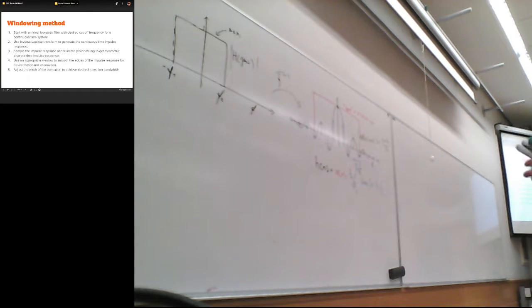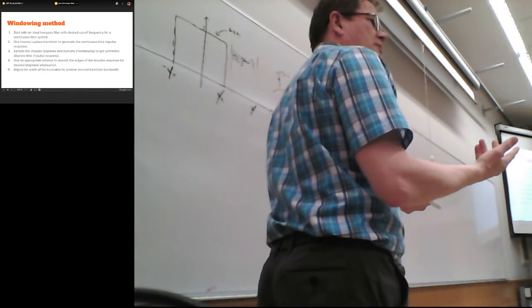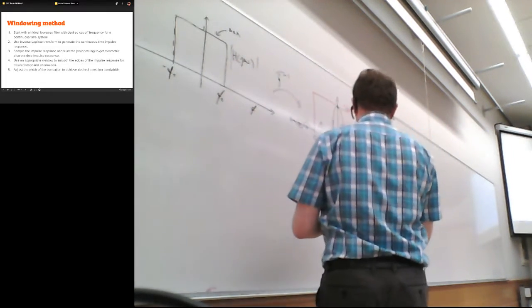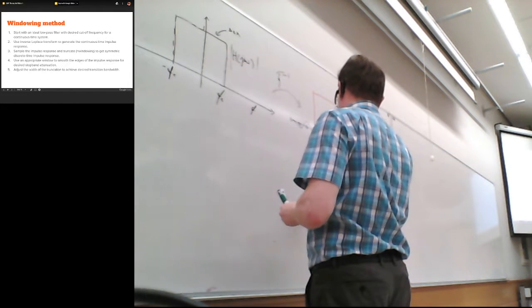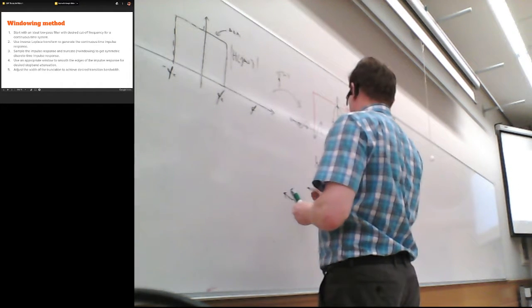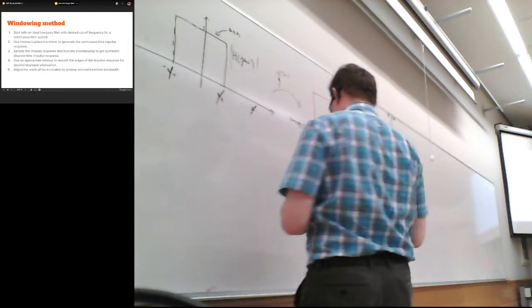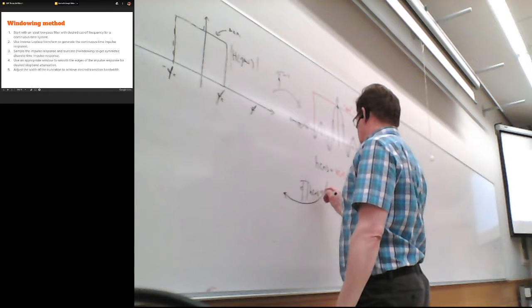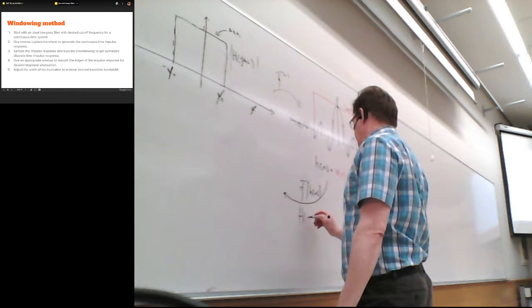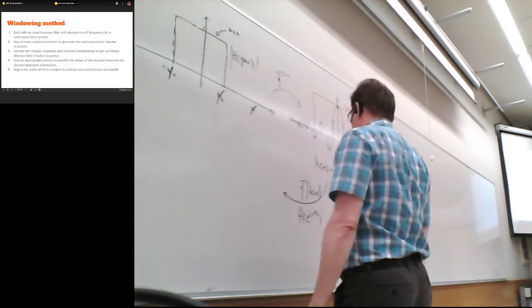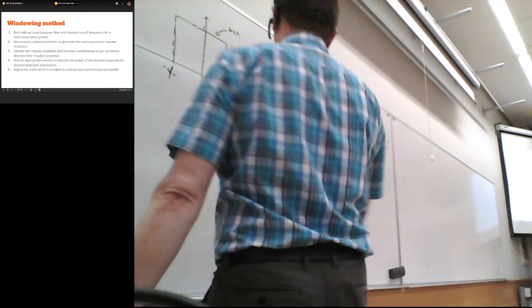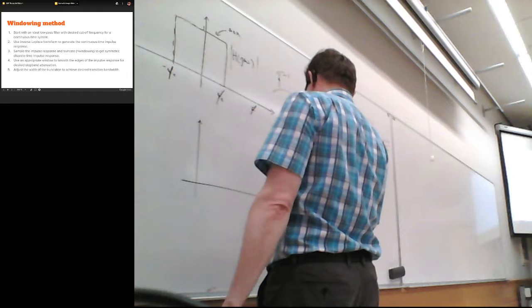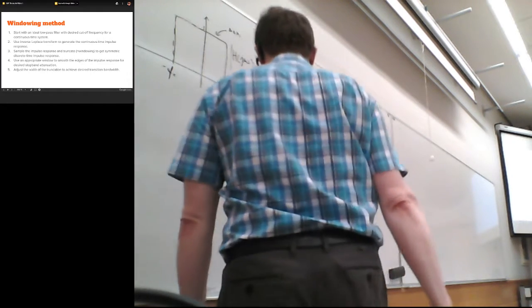Okay, so the next step is to test how close we actually got to the original design. So what we do for this impulse response, we'll do the Fourier transformation or calculate the amplitude response, to see how close we got. Fs over 2, Nyquist rate.